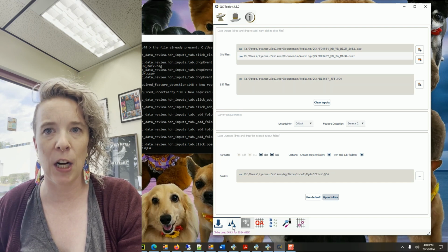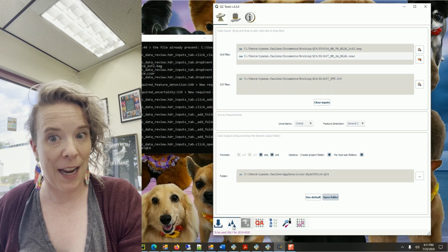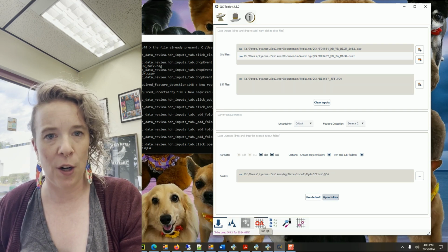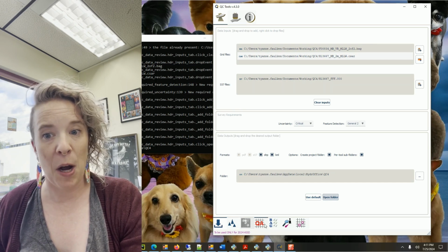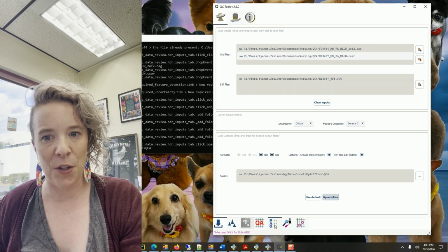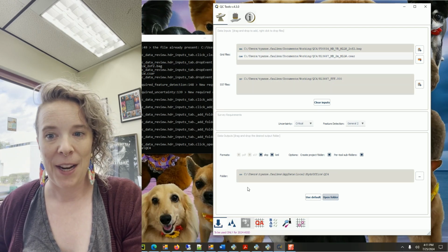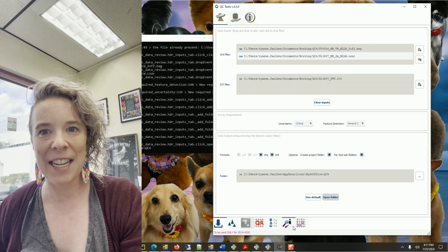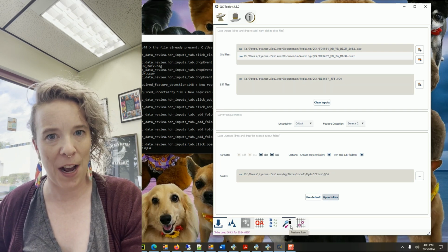So depending on what inputs you have here, if you have grid files loaded, you can then access your Flier Finder, Holiday Finder, and Grid QA tabs. If you have a BAG loaded, these will also be available, and the BAG checks will be available for you. And if you have your grids and an S-57 file, you can then navigate to your Valsou checks.